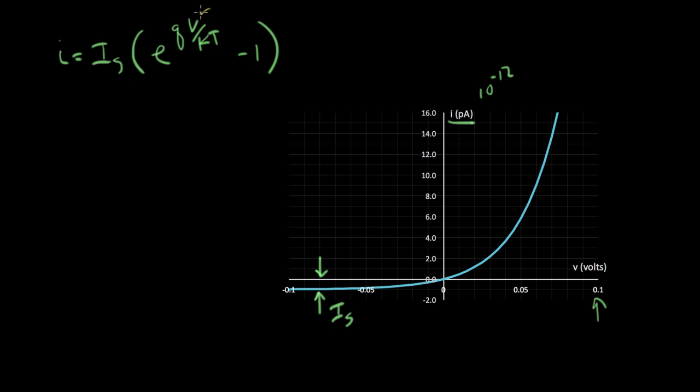If we look at the diode equation and you let V go negative, what happens is this term here in the diode equation becomes very, very small compared to 1. And what's left is IS times 1. And that's what we're looking at right here. This is a really small current. As you can see from the scale here, it's down in the low picoamps area. Almost all the time you can ignore this current and just treat it as 0. Now I want to use a diode in a circuit, and we'll see how we solve circuits that include these nonlinear diodes in them.